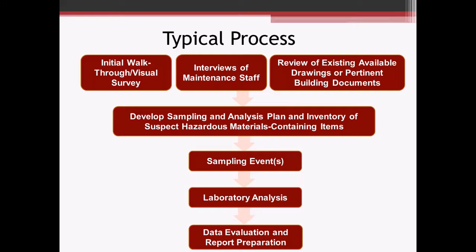From that point, you develop your sample analysis plan, you inventory your suspect hazardous materials containing items. We'll go through in another slide the difference between what things you might inventory only and what things you might sample. So we'll get into that a little later. But then from there, once you have developed that sample analysis plan, you do your sampling event, submit samples for laboratory analysis, and then finally evaluate that data and generate a report that the end user can read, review, and understand what you have at the facility.